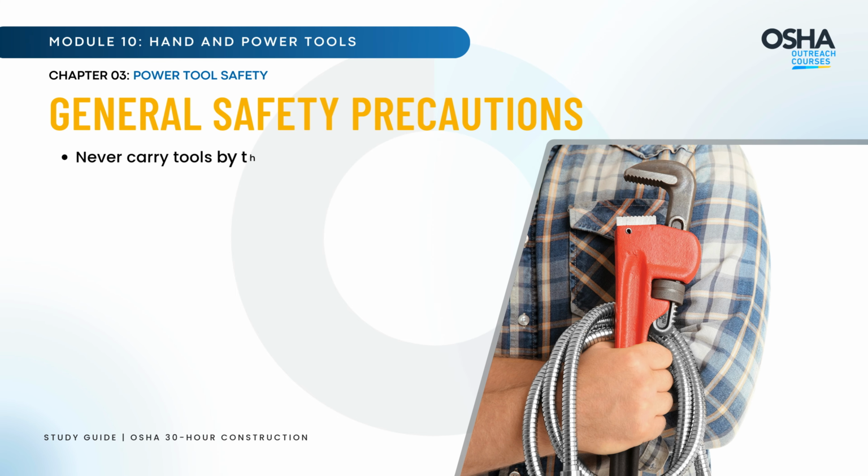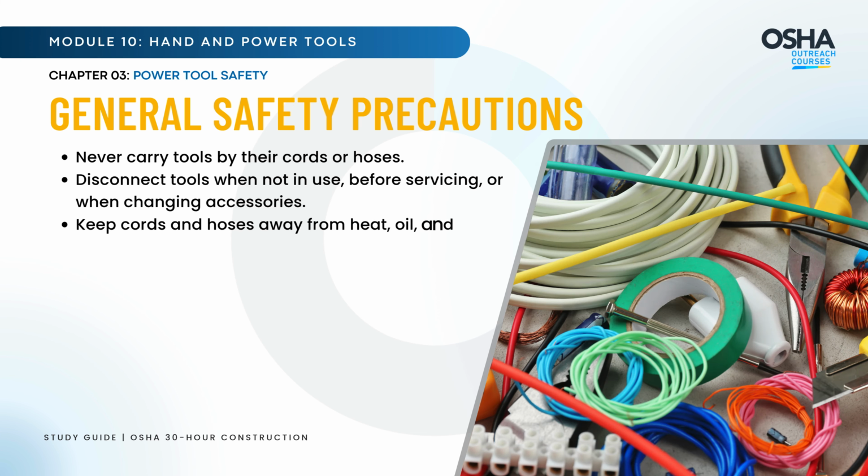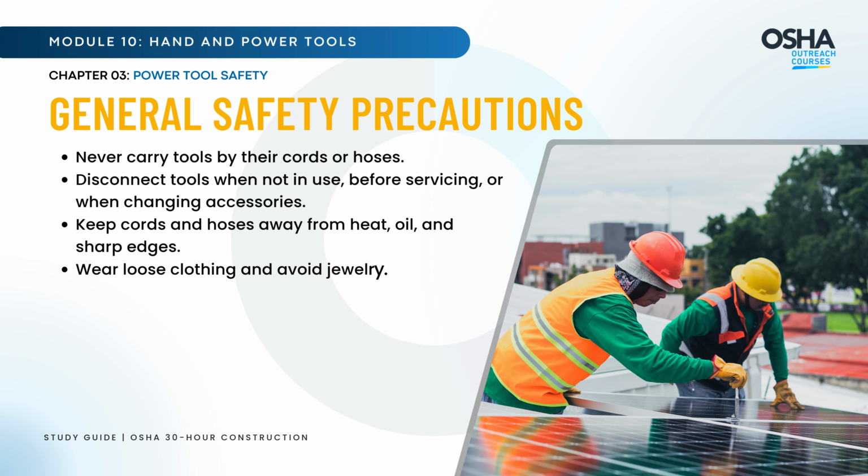Never carry tools by their cords or hoses. Disconnect tools when not in use, before servicing, or when changing accessories. Keep cords and hoses away from heat, oil, and sharp edges. Avoid loose clothing and jewelry.